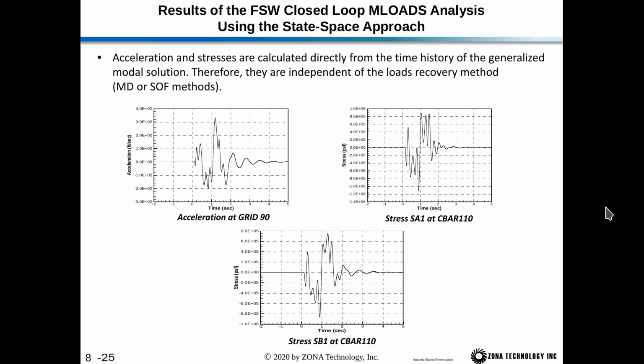These are the results. So the acceleration and stresses are calculated directly from the time history of the generalized modal solution. Therefore, they're independent of the loads recovery method. So our acceleration at grid 90 is here. We've actually started the simulation at time -2 seconds.